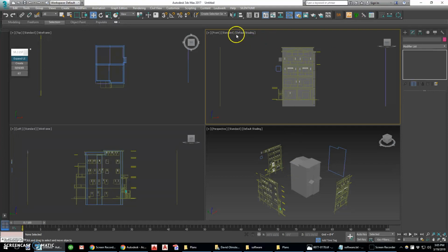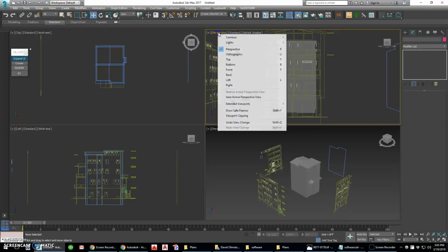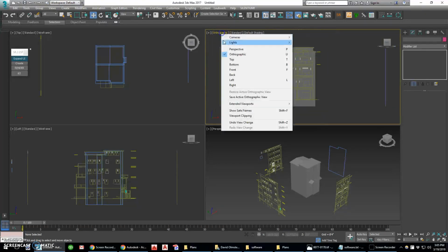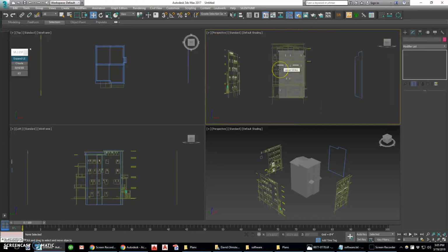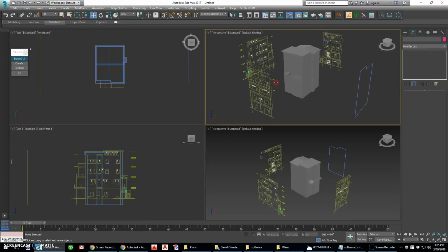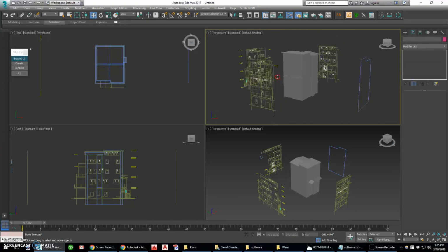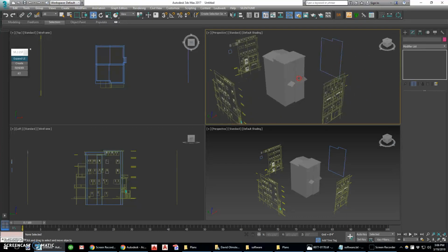This view up here, I'm in an orthographic projection right now. I want to hit P on my keyboard. That changed me into perspective. I guess you can probably change it up here too. I just always hit P. Orbiting on here, I'm sure there's an orbit icon somewhere. I tend to use Shift and Alt, and the middle mouse button does it here. You have to experiment. All these programs use Shift, Control, right mouse button, but this is Alt, middle mouse button.